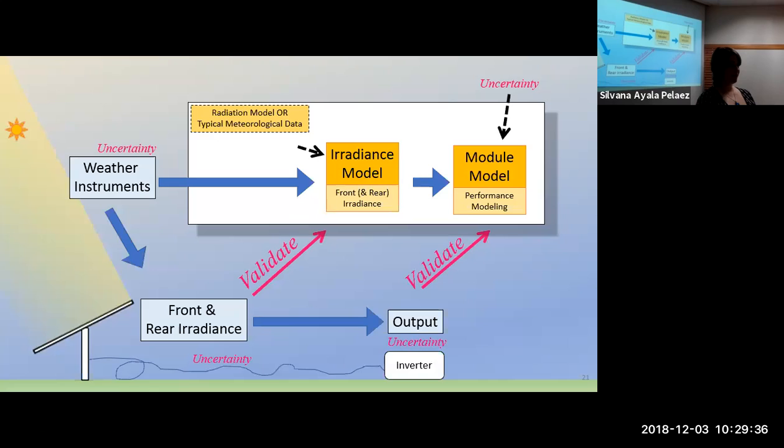That's not exactly true. It's true if you average over 20 years, but if you look at the first 5 years, it's not a linear line. It's a double exponential, in fact. So what you find is that for the first couple of years you would vastly overpredict your power production, and over 20 years it averages out. But for the first 5 years you'd be way below what you thought you should get.